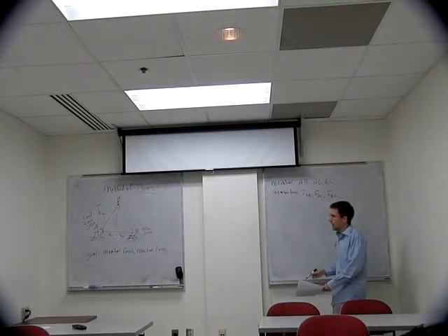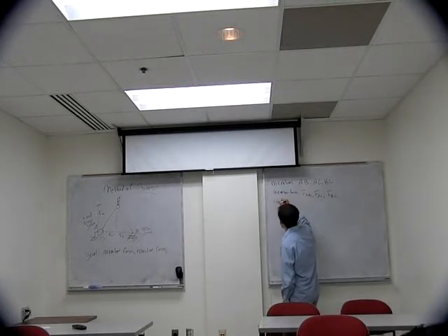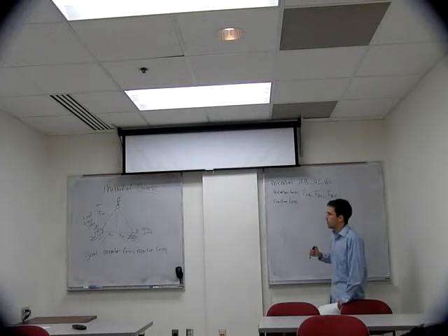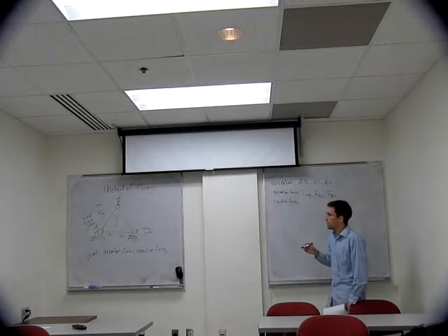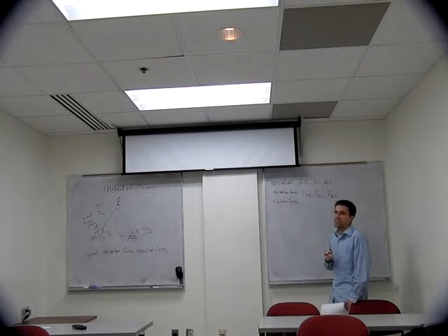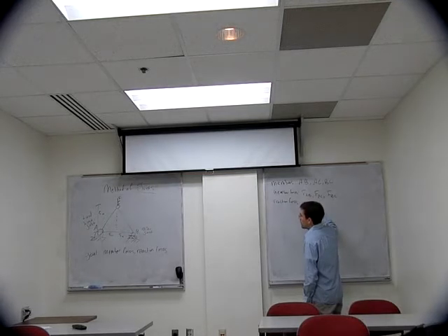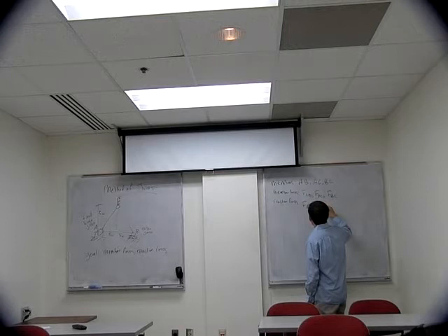The other forces that we have are our reaction forces. We only have two joints that have reaction forces, A and B. A fixed hinge joint has a reaction force in both the X and Y direction, so we have FAX and FAY.